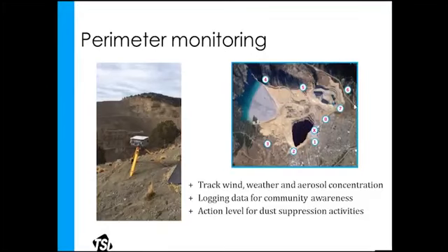But I'm trying to show here we have a community, a pretty large population center, and a pretty large open pit mining activity going on around it. What this customer had done is, the community was concerned about dust. So they actually have a line of DustTraks measuring, not really the perimeter, but along the whole ridge line where the community lives, and just seeing, when they do a bunch of digging and blasting, are there raised aerosol levels? They publish this data for the community, which shows that there really isn't any change from their activities.